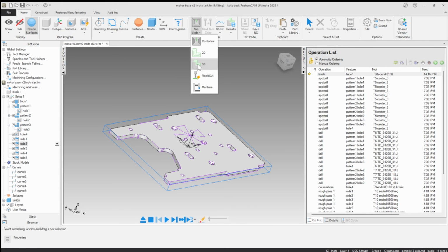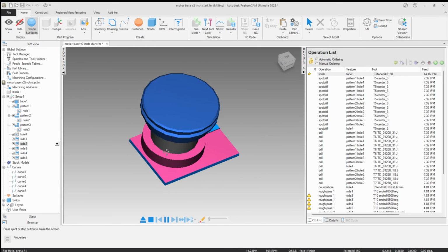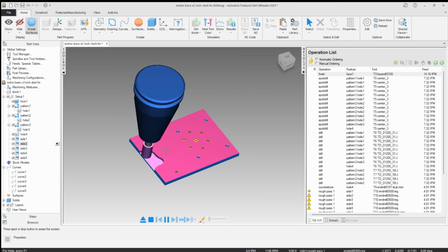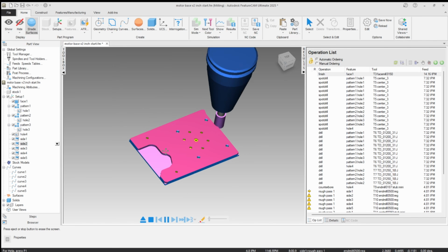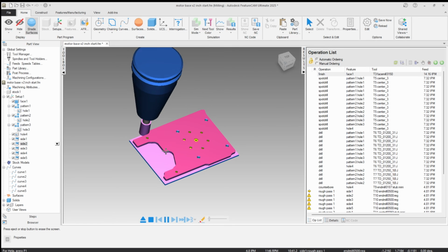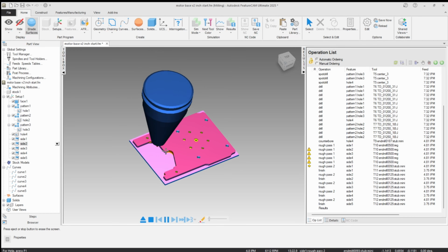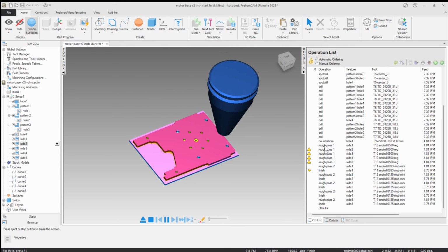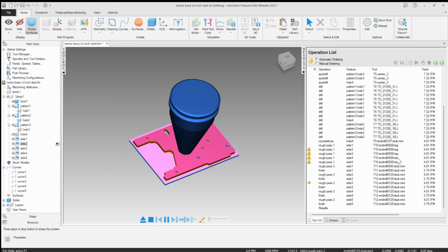Let's go ahead and watch this in 3D, okay, and watch the arrow. Now 3D will actually help us for any collisions we might have. I don't expect any on this particular part, but if we were rapiding a tool into an area where we haven't machined already, or if we rub the shank or hit the holder, as you can see there's a holder displayed here, those would be collisions. There are those warning triangles again. It literally jumped past those. It's not going to output these in the code, right?